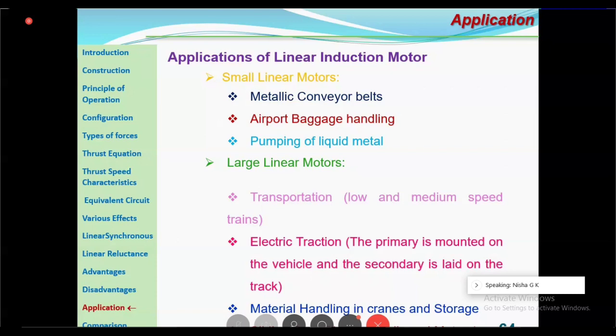Aravind is asking, what is specific magnetic loading? Specific magnetic loading comes from the total magnetic loading. The total magnetic loading is the total flux around the armature periphery at the air gap. From that you get the specific magnetic loading, which is the average flux density over the air gap of a machine. So the average flux density is the total flux around the air gap divided by the area of the flux of the air gap.